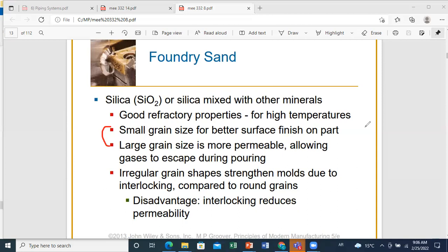What we mean by this: let's say you have a certain shape to produce, and the mold is constituted by a certain material. If you have a lot of curvature in your final design, you should have small grains of your mold material in order to be able to capture these curvatures. Because if you have large grains, this leads to some voids. So the larger the grains, the more voids and inaccuracy, and the accuracy of your finish will be reduced.